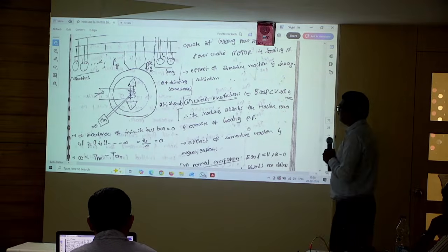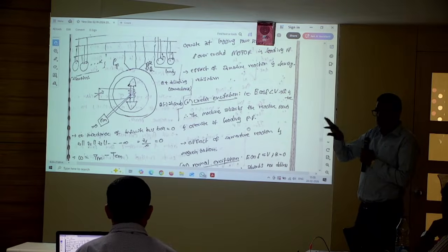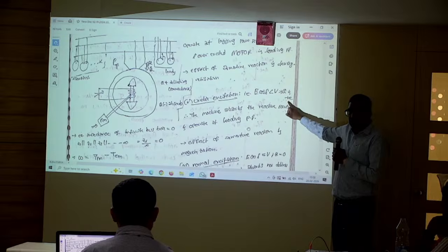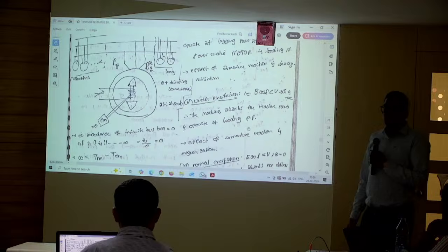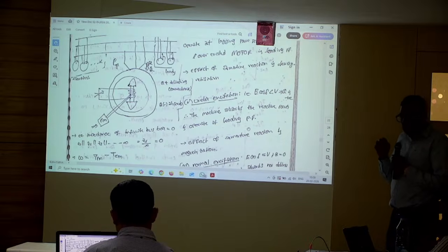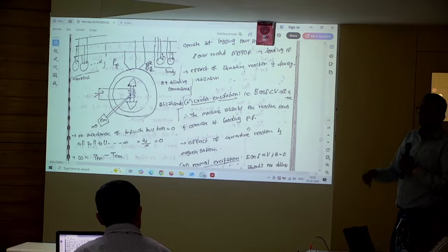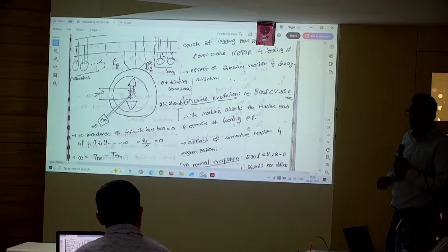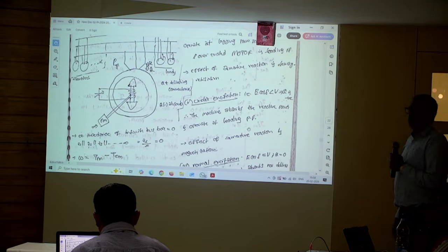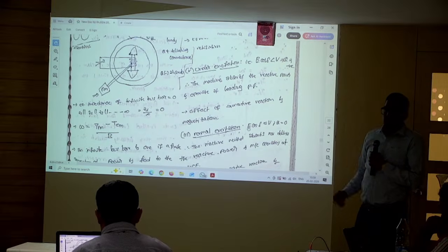Next, under excitation: if E cos delta is lesser than V, and we assume load angle delta is towards 0, cos 0 is almost 1, then Q is negative. Magnitude wise the same. What is this negative indicating? The machine is absorbing reactive power, which establishes flux. In order to keep the magnetic field inside the alternator constant, as per our EMF equation, when excitation changes, the resultant flux is maintained at a constant value by exchanging reactive power, either into the infinite bus or taking from the infinite bus. During these changes, with normal excitation, Q is equal to 0. Normal excitation, no sharing of reactive power.